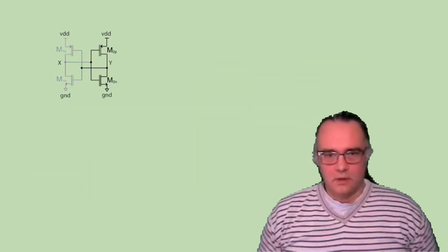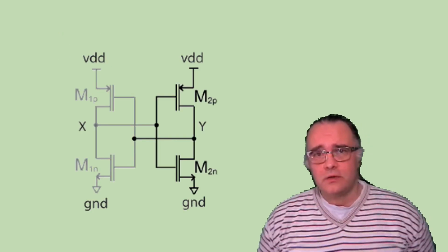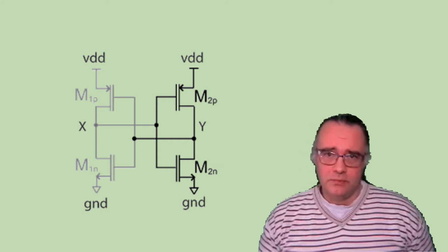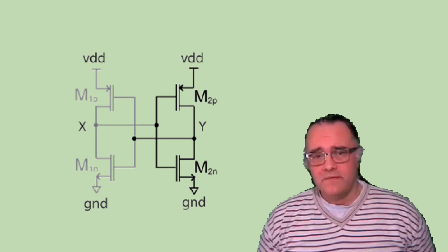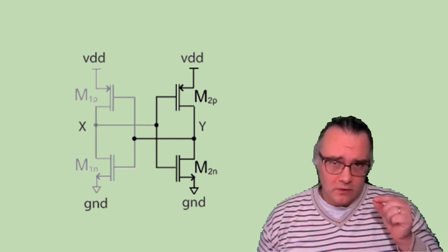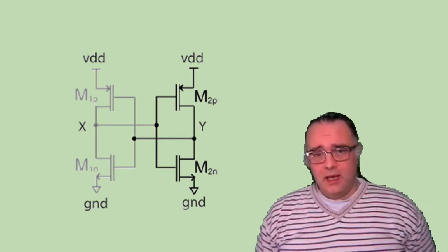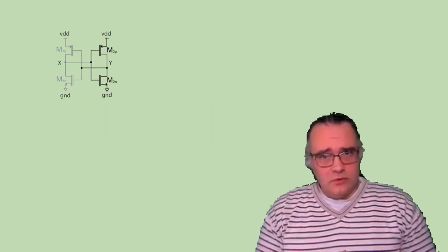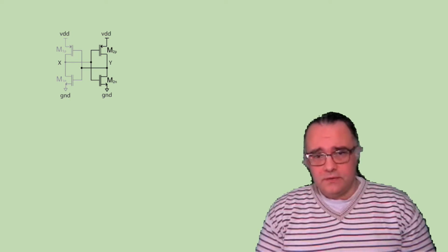And this is an example of a latch, a very popular example. This circuit is used often. Two CMOS inverters that are locked in a positive feedback. The input of one is the output of the other and vice versa. So we have two signals, the signal node X and the signal node Y. And we can draw the input-output characteristic of one of the inverters.